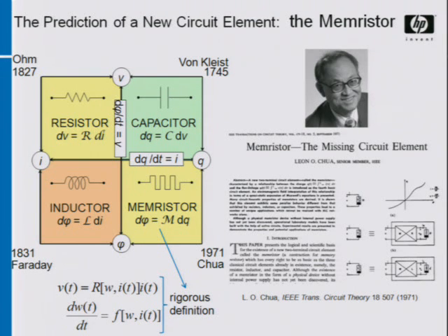And there's something that you should note about it, and that is it requires two equations. All right? Because memristors, as were so eloquently stated by actually Steve Kang, are dynamical devices, and therefore they have an explicit time dependence that you must account for when you are looking at how the devices work. So you require an equation which describes the essentially instantaneous conductance of the device, if you will. What is the relationship between current and voltage at any given point in time?